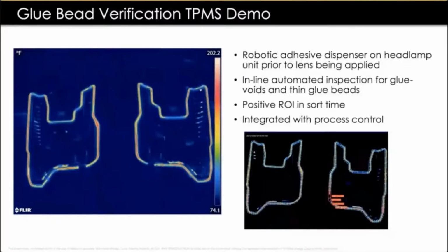What would end up happening was the channel in which the adhesive was applied, imagine a U-shaped channel. The parts, these plastic parts coming out of the injection molding process, had warp into these bridges and warpage on the walls. So when the robot went to apply them, some of that adhesive got placed not in the bottom of the channel where it's supposed to be.